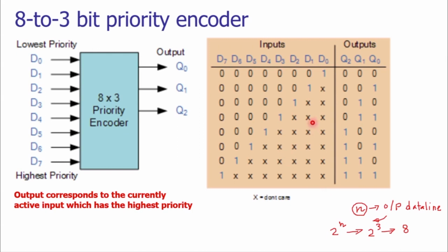So we have to develop the logic gates and OR gates. If D1 to D7 are showing low level input and only D0 is showing high level input, that is 1, then the logic gates based circuitry will give the output as 0, 0, 0. In the next case, the logic circuitry will produce the signal as 0, 0, 1.